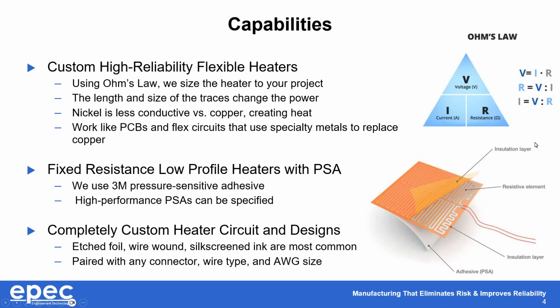Additionally, you need to get power to these somehow. Most heaters have wires terminated directly to the heater pads, and those wires can be various off-the-shelf UL spec wires to custom wires, any combination of color, gauge size, and overall length.